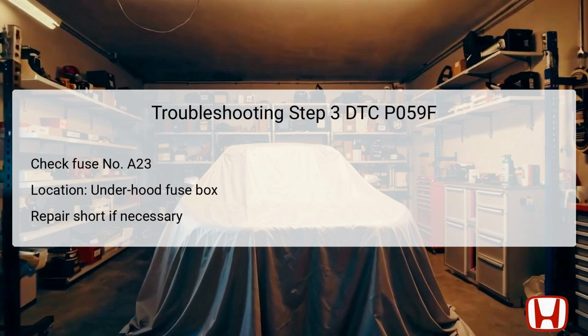In the third step of troubleshooting DTC P059F, you need to examine fuse number A23, which is located in the underhood fuse relay box.